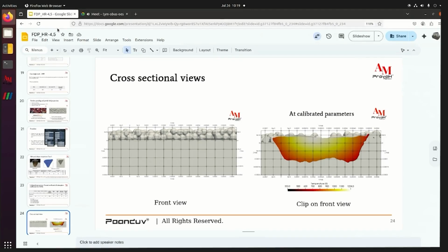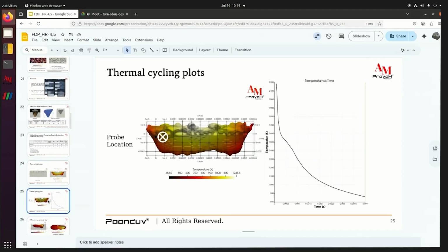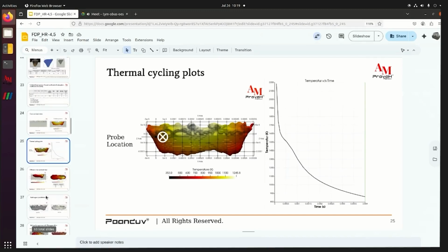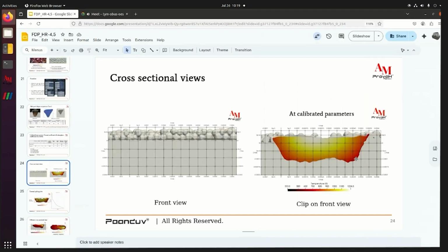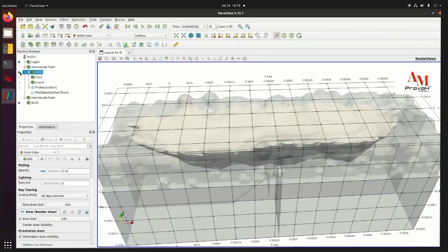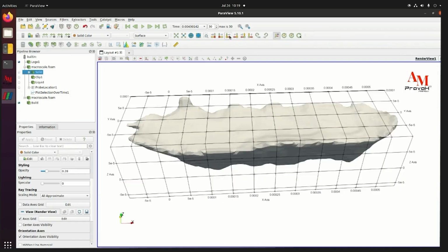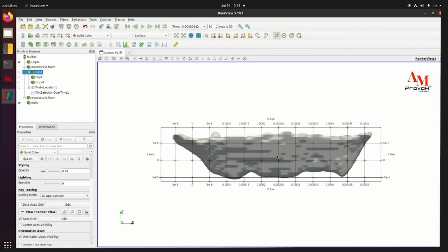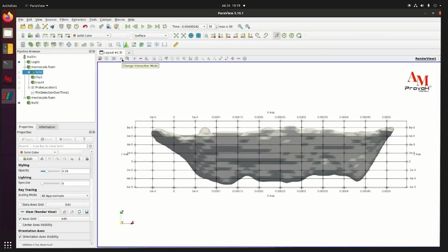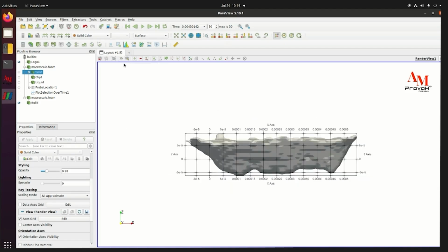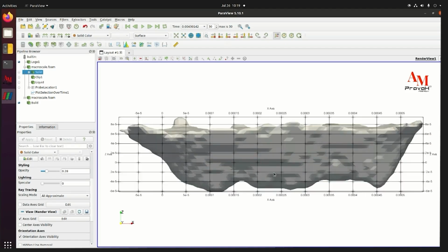Okay, so now come to the second view. Okay, so we can measure the width and depth also, which is quite important here. So let's deselect this solid and take the build and take the Y direction and make it 2D. Okay, from 3D we have to make it 2D so that it will not move, because it's very important that dimensions are taken very carefully. It should not rotate in any direction. So just make it 2D. Here the 2D is written over here.